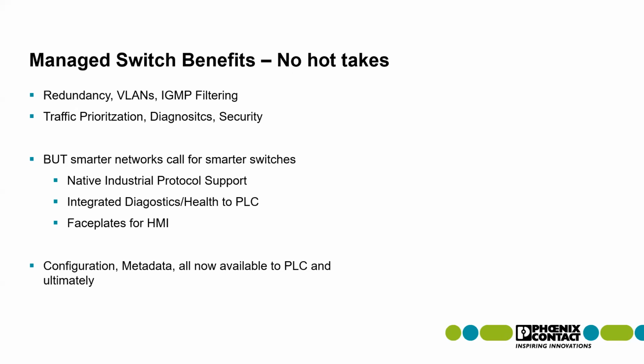And again, not to steal an upcoming presentation's thunder, but having a flexible control platform that gives you several different means and several different mechanisms to control not just your application, but your infrastructure is a very smart way to do things, and it is a very IIoT friendly way of doing things. So in addition to having the integrated or the native industrial protocol support, it does allow you to integrate the diagnostics, the health, the activity of your devices, of your infrastructure switches into your PLC control platform, which means that you'll be able to see what's happening and react to what's happening to your infrastructure in the program, and not have some operator get a red light showing up on an HMI and have to decide what they want to do, how they want to react.